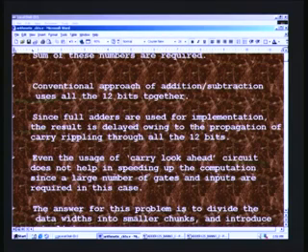Since full adders are used for implementation, the result is delayed owing to the propagation of carry rippling through all the 12 bits. So when you add 2 bits, it will generate a carry, that carry is added to the next second bit, and so on, the carry propagates.